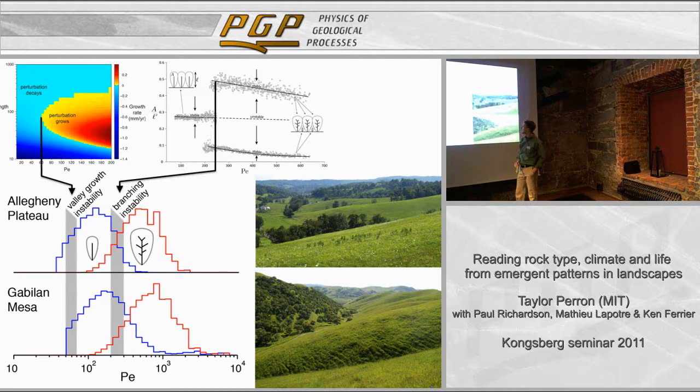And make a comparison. So the first thing you note is that the transition, the gap between the modes here, first and second order drainage basins, falls pretty close to that critical value of about 250 that I inferred from this stability factor here. Works a little bit better in Pennsylvania than it does in California, but you're generally not off by more than a factor of 2.